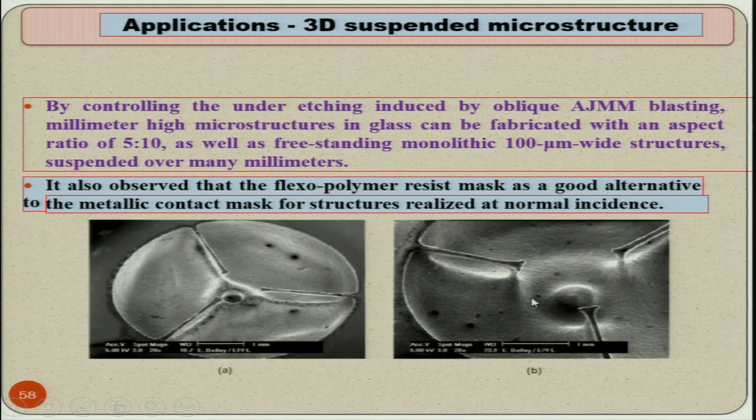It depends upon the material of the component being machined, because according to the hardness and type of the workpiece material you are going to decide the pressure of the air abrasive jet, and pressure of air abrasive jet will decide what kind of mask material you should use. So, depending upon these parameters you can decide cheaper or expensive mask, because the mask also should not wear out fast, otherwise you cannot use it again and again.